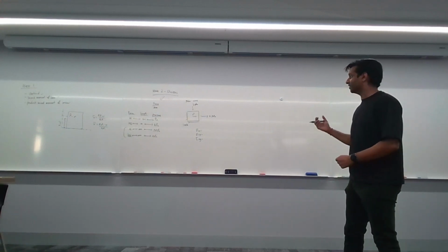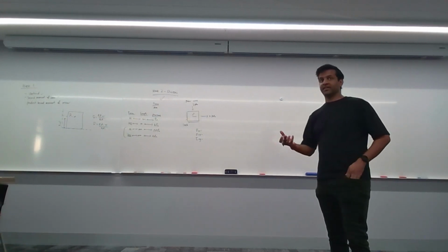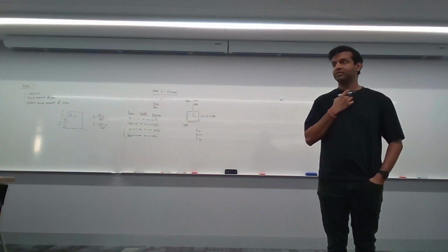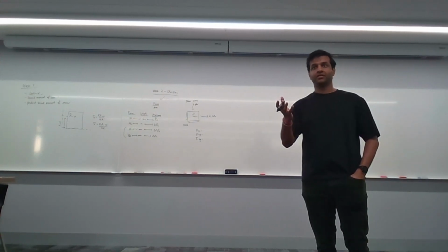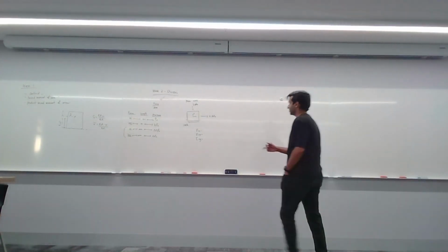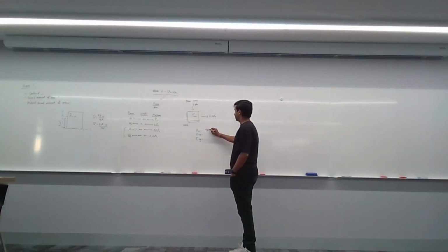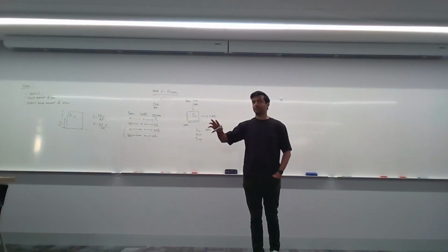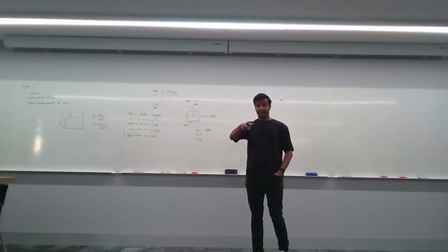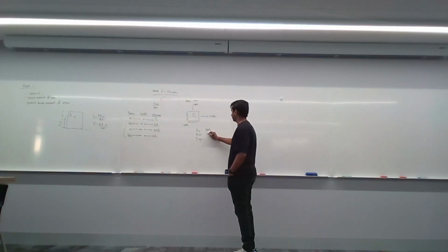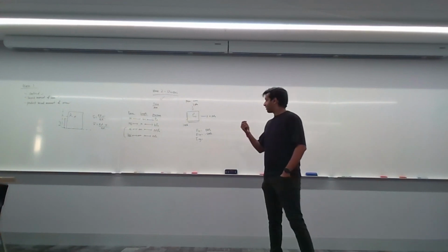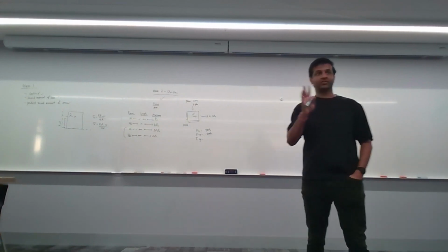All right. Can anyone tell me what is sigma xx? Positive or negative? So is that tension or compression? Tension. Okay. So this is 4 MPa. All right. Sigma yy? Positive or negative? Negative. Right. Compression? Okay. Negative 3 MPa. All right. Tau xy. We know it's 1 MPa. Okay. Positive or negative?